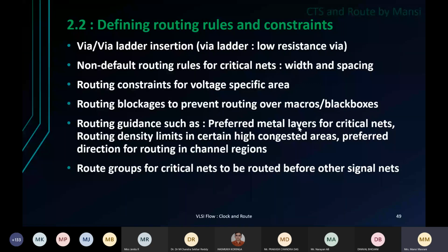Those pins all have non-default routing rules, same as clock. Not exactly as constrained as clock, so you might not use double width over there, but you might end up using double spacing for those nets, because you want to bring those nets to the flops in their original signal shape. Integrity should be very close to clocks. So for that also we use non-default routing rules.